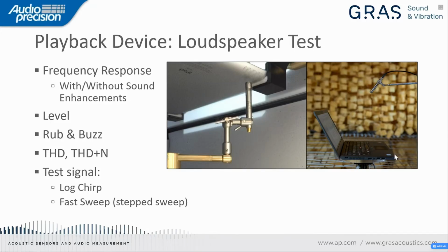We can measure the frequency response of the laptop and tablet loudspeakers with and without the different sound enhancements at different levels. So we can test, for example, the linearity of the speakers at different SPLs. We can, of course, measure the level generated by the speakers using different test signals.